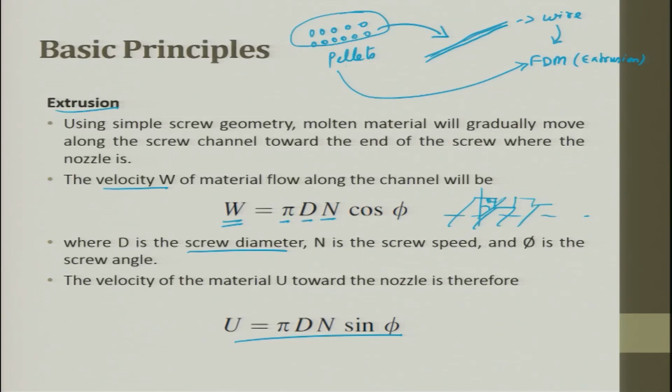So people have started directly using these pellets instead of the spool feeding nozzle and other things. You will have a hopper as used in an injection molding machine, then a screw. The pellets will pass through the screw and exit through the nozzle, and then lay on the table. So this is another process where people have started working. Why?